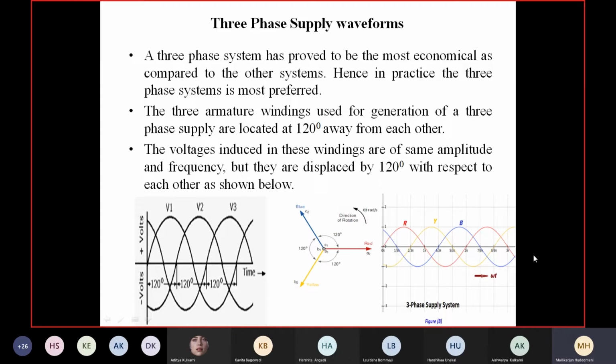Then second group Y start late by 120 degree. You can see here, its beginning on the 0 scale is 120 degree later. It makes its one cycle completion. Then similarly 240 degree later from the 0 mark, it is a B start, means third group. This way RYB, you can see hump 1, 2, 3. In what way they are appearing? R first, Y second, B third. That is called phase sequence. Phase sequence is the sequence of attainment of peak of respective waves.